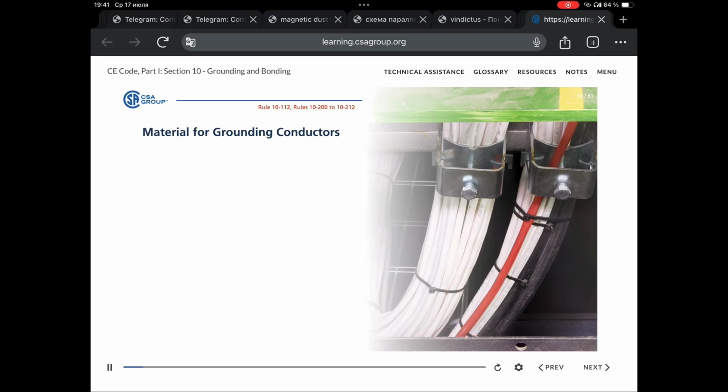Only certain materials that are considered suitable for grounding conductors are permitted to be used. The list includes copper, aluminum, or other acceptable material, permitted to be insulated or bare. The material used for grounding conductors is required to be resistant to or adequately protected against any corrosive condition existing at the installation, to ensure that under all conditions and after years of service the conductor and its connections continue to provide a low impedance path to the grounding electrode.